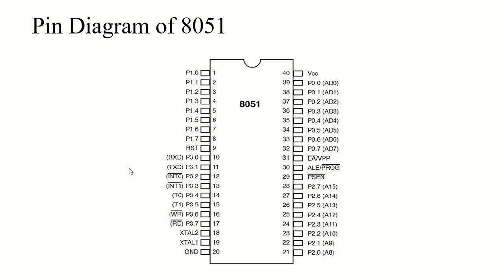P3 does not need any pull-up resistors, just as P1 and P2 did not. But still, P3 is configured as an input port upon reset, and this is not the way it is most commonly used, because port 3 has the additional function of providing some important signals like interrupts.